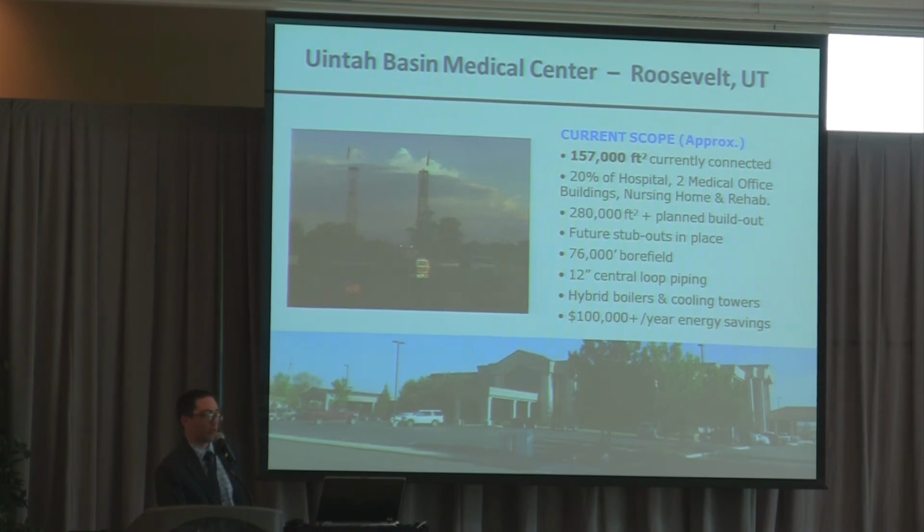About 20% of the square footage is currently connected. The neat thing is they anticipate that they'll be able to connect about 75% of the square footage of the hospital before they have to drill any more loop fields, based on the diversity of the system. So it's, again, performing better than we, as engineers, are conservative by nature.